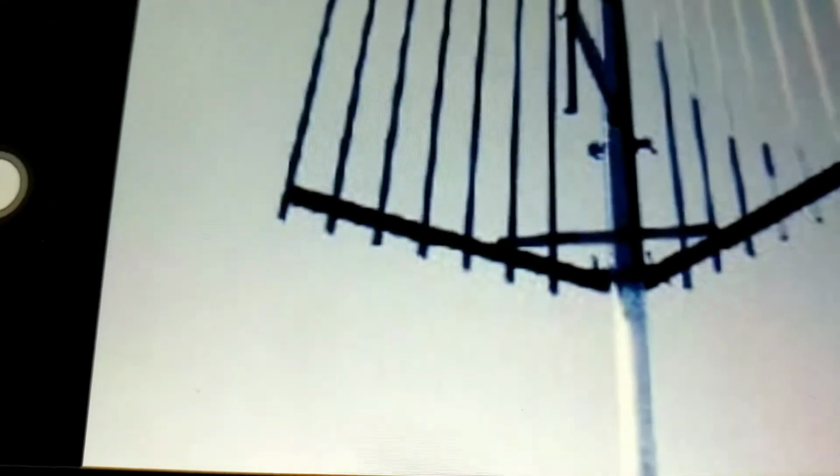The fifth major type will be explained by me, Rupesh. The fifth type is the reflector antenna. The reflector antennas are of two types, the corner reflector antenna and the parabolic reflector antenna. The antenna that comprises one or two dipole elements placed in front of the corner reflector is known as the corner reflector antenna. The radiating surface of a parabolic antenna has a large dimension compared to its wavelength.